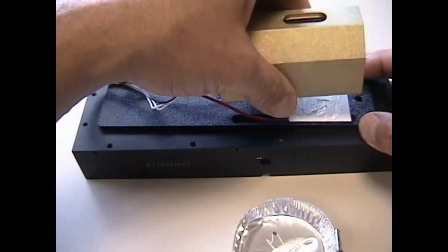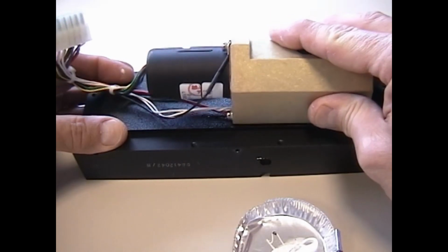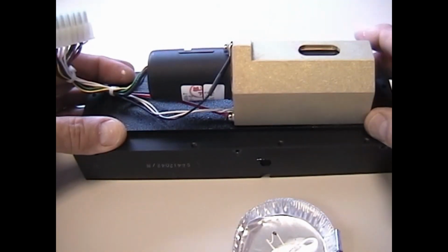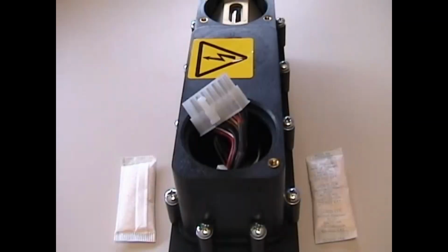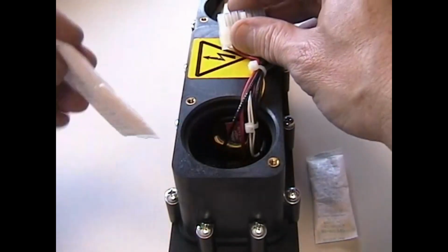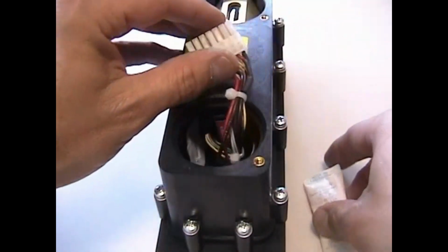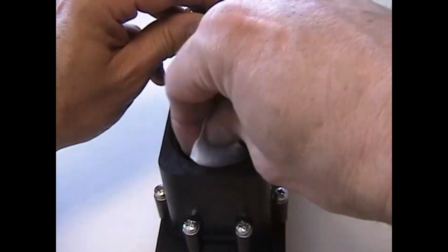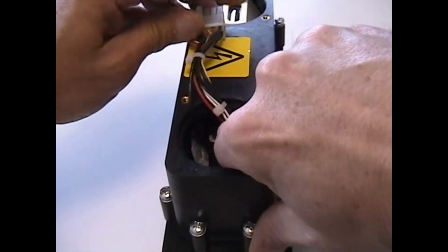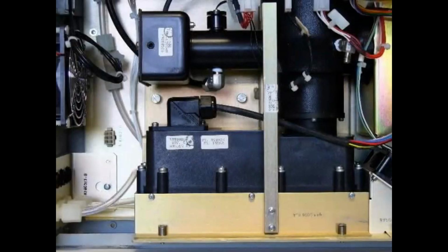Place the PMT block on top of the cooler and reinstall the block retaining screws snugly. If you over-tighten these screws, you will crush and permanently damage the TE cooler. Reinstall the PMT housing cover and insert 2 new desiccant packs. The desiccant packs prevent condensation on the PMT, and it's not recommended you reuse the old ones. Reassemble the optical bench and reinstall it into the sensor tub.